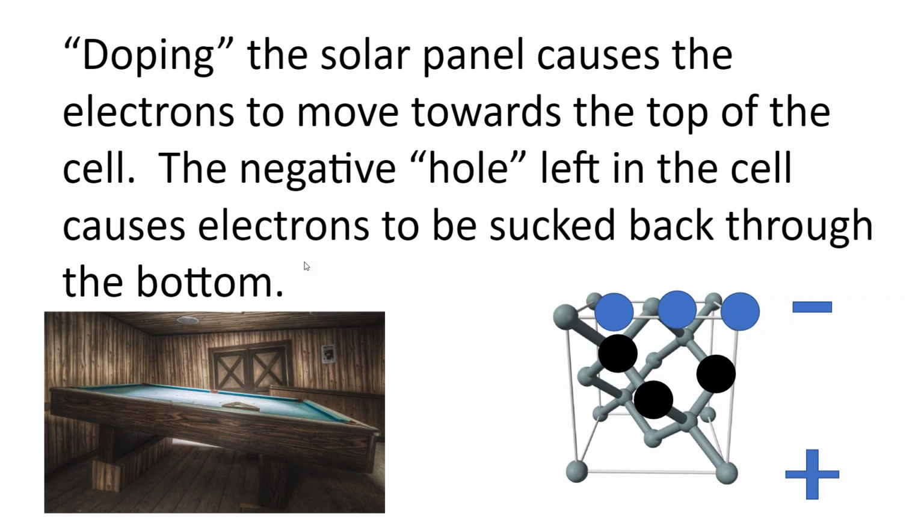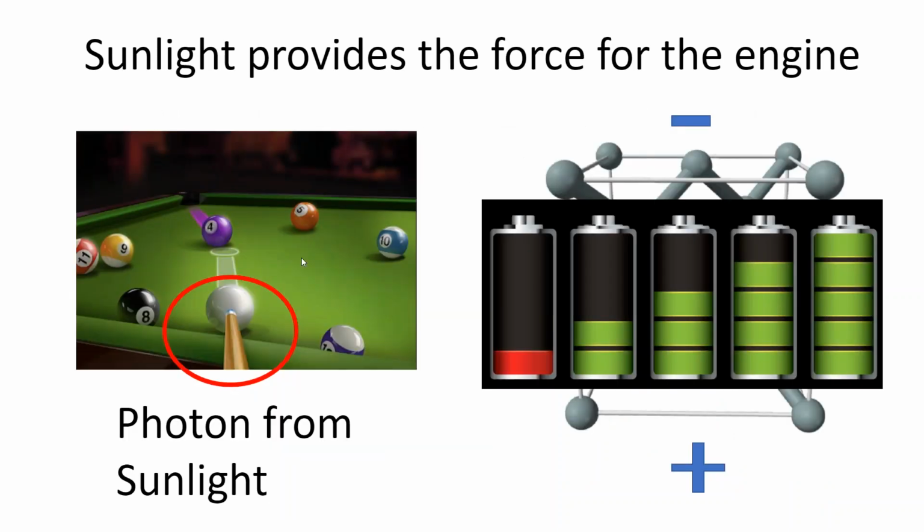They take that photovoltaic surface, the silicon, and treat the top side and the bottom side with dissimilar elements, and that creates the disparity that causes the electrons to tend to move to one side and away from another side. So the sun comes up, the panel gets a positive and a negative, and the sun goes down, and everything falls back into place. In this case, it's like a battery that's fully charged, except it's fully charged when it has full sunlight, and then it has different power levels as well.